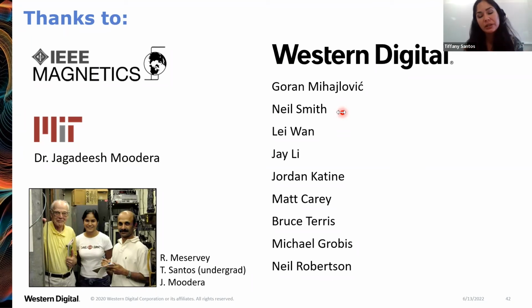For this reason, you can expect that the only thing you're going to have left after using it to mill your MRAM bits is tantalum nitride. And tantalum nitride is a conductor, so we choose that so that it can act as a top contact when the process is done.